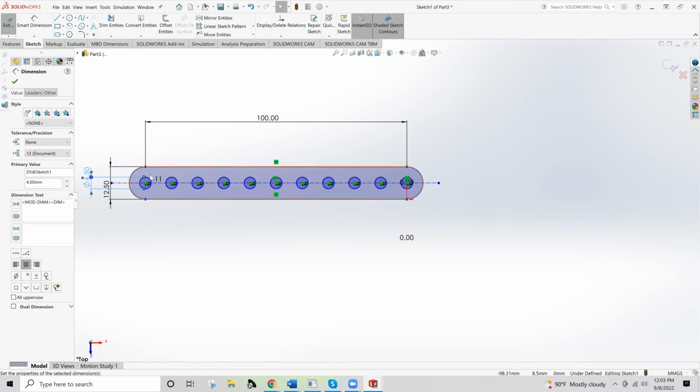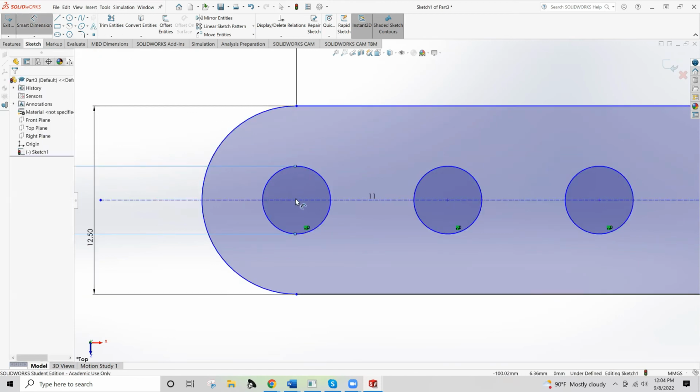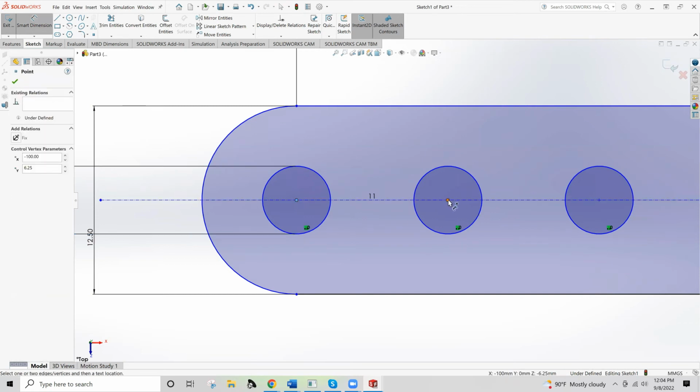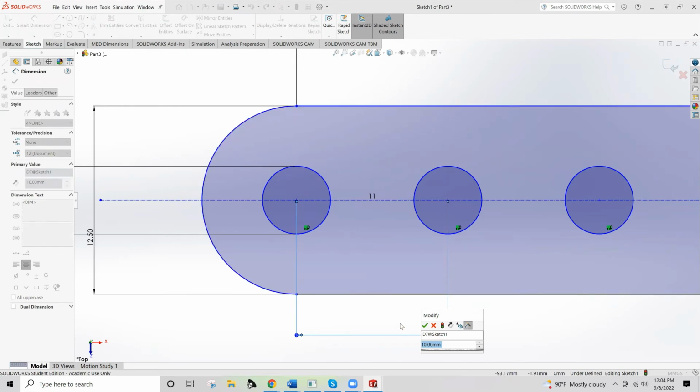Maybe some of those features work a little better in the newest version that we're running now. I'll let you know as I come across some of those. But the good habits of old have been, make sure that you get your geometries and your pitch, meaning the center to center spacing, right. So the distance from here to here, I'll measure it just so that you guys can see. This will probably give me a flag saying this is overdefined, but since I don't have a fully defined sketch, this won't yet. So 10 millimeters. Yes, that is correct.